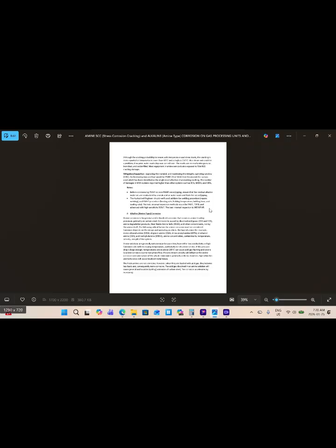Authorized engineers should verify and validate the welding procedure for weld repair and confirm the post-weld heat treatment procedure, the temperature of the post-weld heat treatment, and the retention time in the post-weld heat treatment, which is very, very important. The heating and cooling rate of the post-weld heat treatment procedure is also very important.